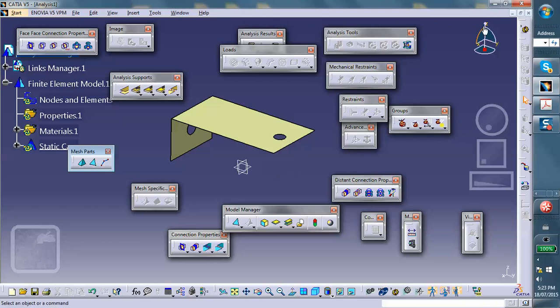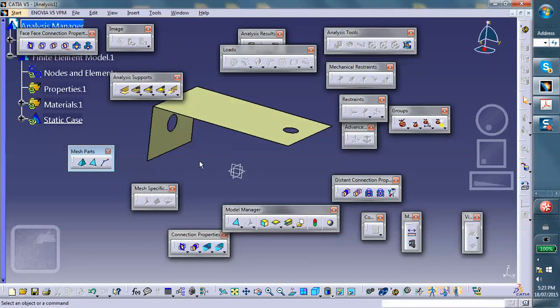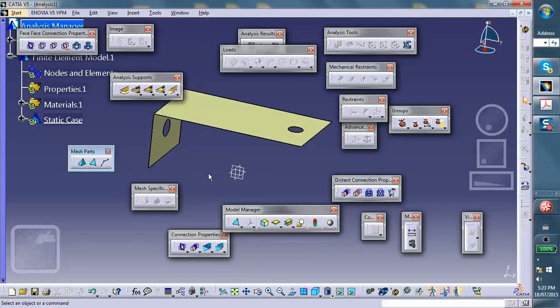In this case, the YZ is the plane of symmetry. So you have to cut it like that and put the appropriate boundary curve or appropriate restraint on it. Now remember, just cutting it is not going to cut it. You have to put the appropriate restraints on those imaginary edges that you create. But since I want to be in line with what's done in the book, at least for this try, I'm not going to cut it.